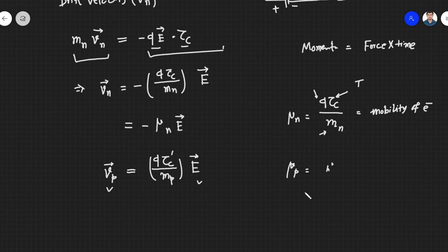Those atoms will be ionized even at room temperature. So they will create a different potential well, a different force environment, right? Because electrons and holes are charged particles, they will be affected by any surrounding charge present nearby.